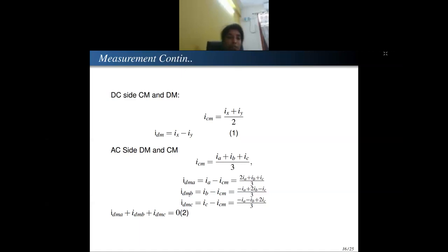So we measure both. There is no prediction needed in differential mode. It is easy to tell which noise is dominating and so on. But in common mode, it is difficult because it is system dependent. So what generally people do is, I measure the common mode component of my own system. I measure the differential mode component of my own system. And then I set my bar of how much attenuation is required, and which method I would adopt for my system to mitigate and meet the standards. If you are looking to meet the standard, you have to look at how to meet the standards further.